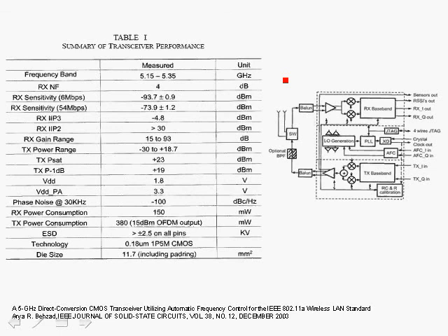One other thing is that many of these direct conversion receiver architectures use different ways in order to combat DC offset and combat IQ imbalance and other issues. I will refer you to the various IEEE publications and other publications so that you can actually look at the various architectures and the various trade-offs, and especially look at the architectures that use heterodyne versus homodyne or direct conversion.